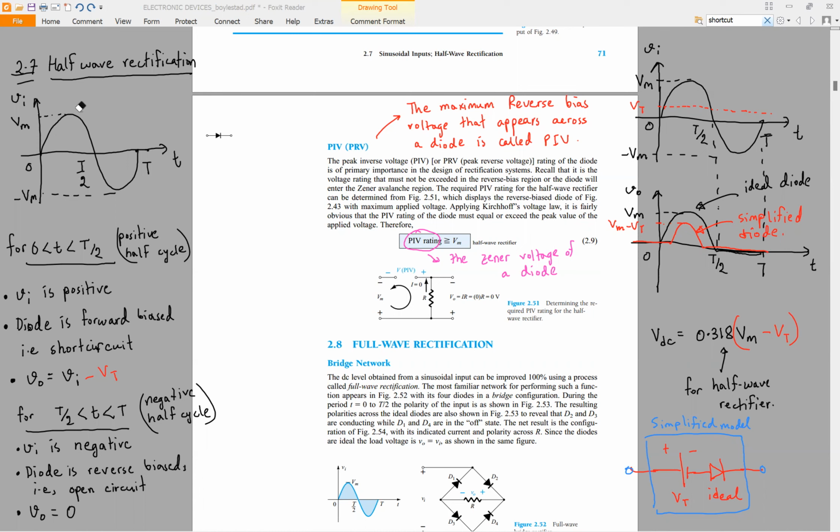Why is the circuit that we have seen before, this circuit, called a half wave rectifier circuit? So this is Vi, this is Vout. As you have seen, when the input is positive, the rectifier allows the positive input to go to the output, but when the input is negative, it blocks the negative half of the input. So that's why it's called half wave.